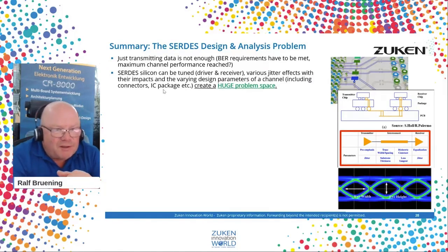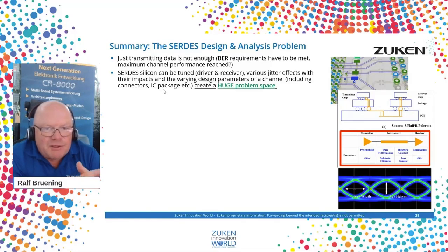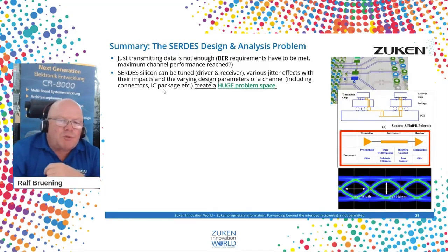SerDes silicon, the PHYs, the FPGAs, the DSPs can be tuned on both ends, on driver and on receiver side. And we are suffering different noise aspects, mainly jitter, by different root causes, and they have different impacts on the eye opening. So this is creating a huge problem space.